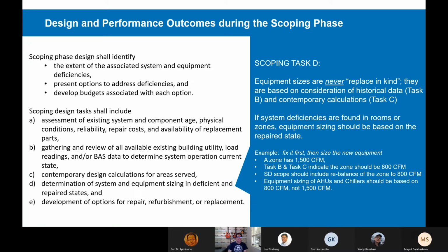Task D is to determine the equipment size, and I need to point out right away that determining the equipment size is pretty far down the list. Equipment sizing is not task A. It's not the first thing that we do. It's soundly down the list. And so saying that the equipment is replaced in kind is never an acceptable option. We want to size equipment based on the assessments, based on the existing information, based on those contemporary design calculations.